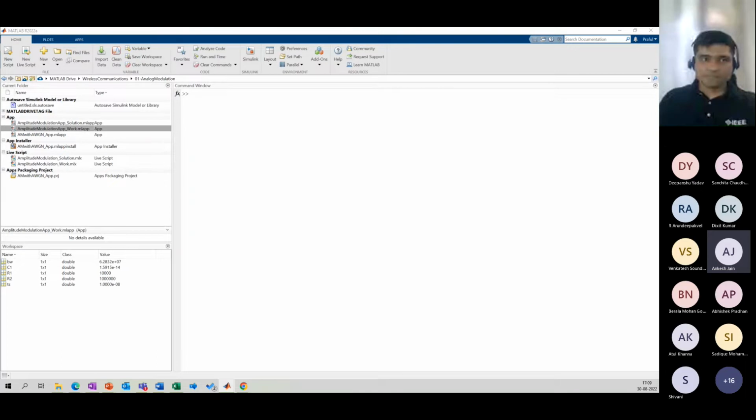Later on, once your architecture is built up, even when you want to see the influence of parameters, those things are pretty fast here because everything is at a mathematical level. Later, when you want to validate the model you have developed, you have to go for a SPICE simulation, because SPICE models are the realistic models which try to model the transistor that will ultimately get fabricated.